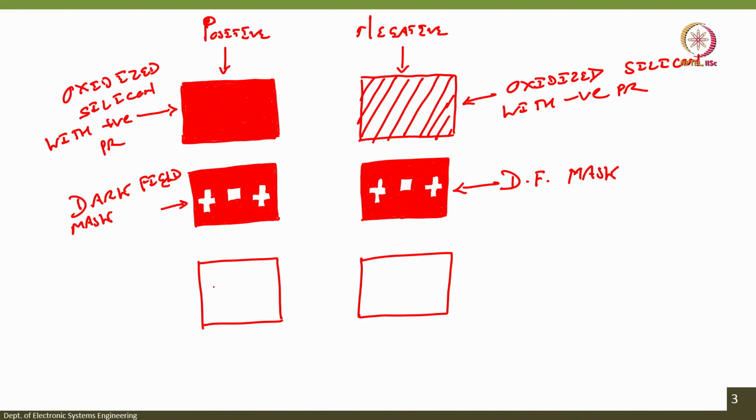That is what we have learned. So, that is what will happen. The positive photoresist from this wafer, the area that is exposed will get weaker and the area which is not exposed will get stronger. So, the final pattern that we get will be similar to our mask. In case of positive photoresist, the final pattern that we get is similar to our mask. Is it correct?